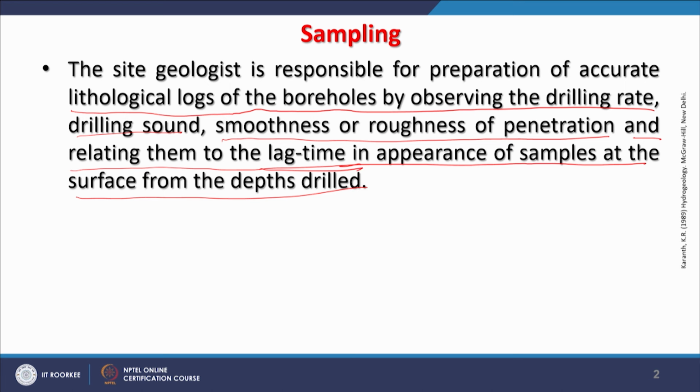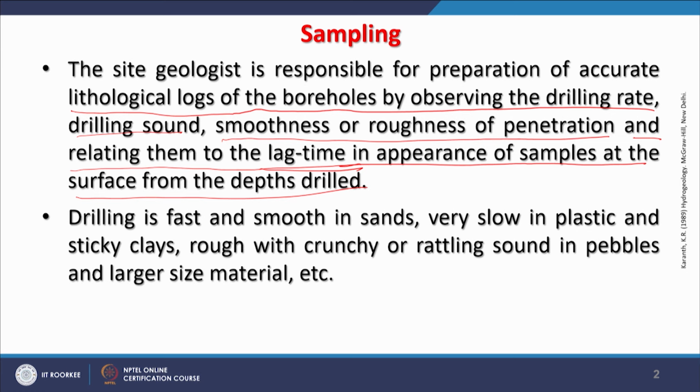Everything is basically recorded, because it is expensive. Again, it cannot be done on the same site or in nearby places, and therefore maximum subsurface information should be collected, because it is a very expensive affair. Drilling is generally fast and smooth in sands, very slow in plastic and sticky clay layers, and rough with a crunchy or rattling sound in pebbles, if you get these kinds of sediments and larger size materials. This can be observed if somebody is adopting fast drilling methods, air rotary, reverse rotary and so on, in an Indo-Gangetic plain like situation.